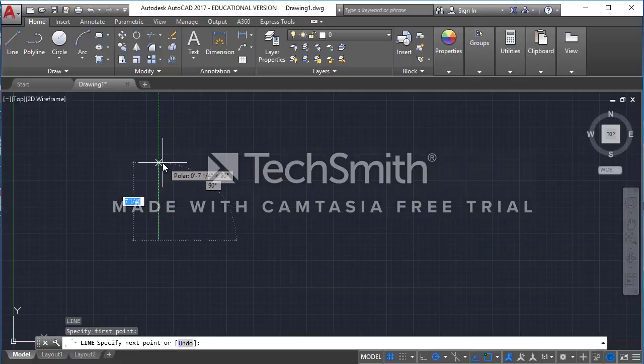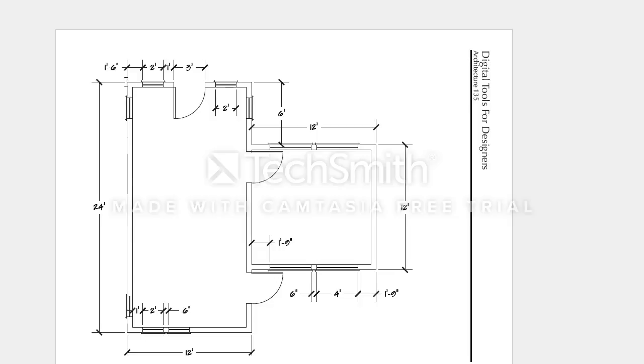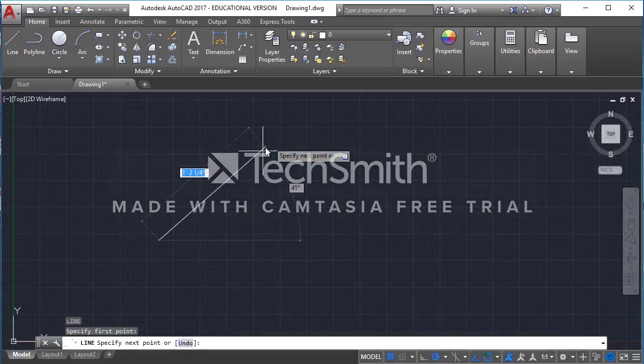Okay, so as you move your cursor around and you want to start to draw your walls, you're going to just move the mouse in the direction that you want the line to go. For example, let's look at my house here. I want to draw this first wall over here. We can see that this is, I think, 2 feet, 4 feet, 5 feet, 7 plus 1 is 8 plus 2 is 10 plus 2 is 12 feet. So our first line is going to be 12 feet long.